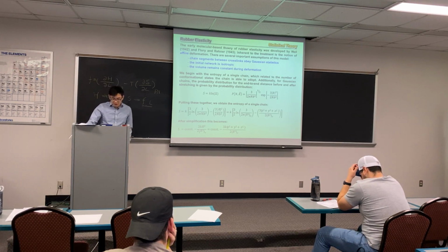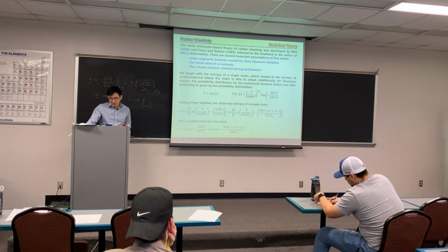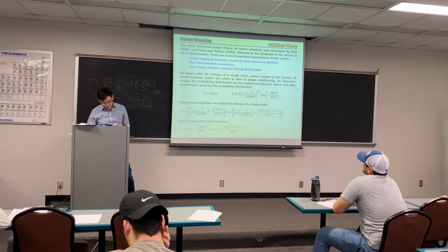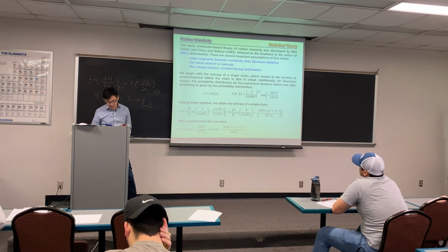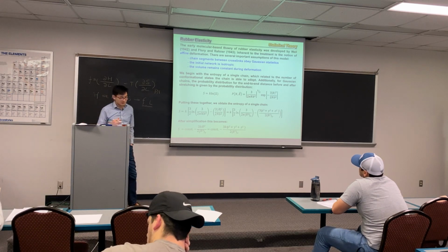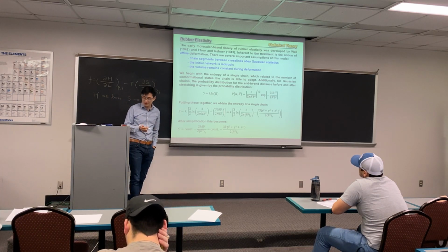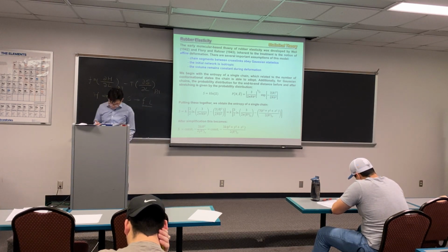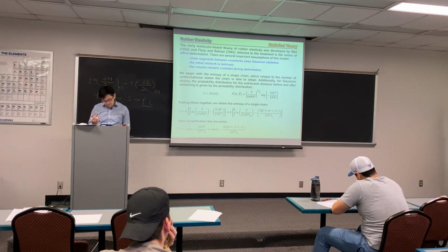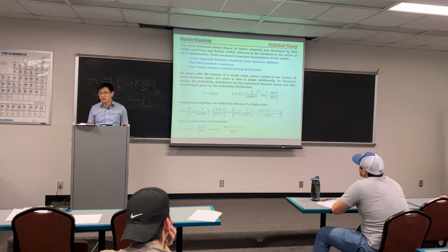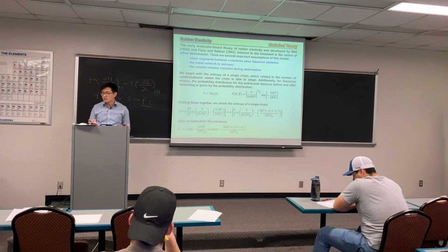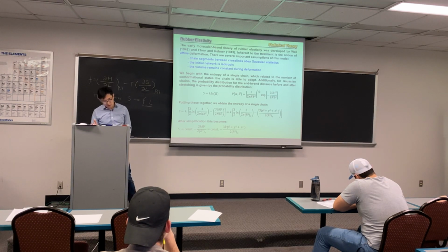In the early days, the theory of rubber elasticity is really based on statistics. In the early days, this was done by Wall and Flory, as well as Rayner. So those three scientists developed the fundamental concepts of how to deform a polymer chain. Again, we will talk about a few ideal cases. Like we talked about the ideal elastomer, we didn't consider the entropy during the deformation. There are a few more notions we need to learn.